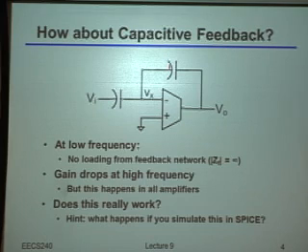Okay? Now, of course, if I have a capacitor, that is going to cause loading onto the output at higher frequencies, because just like any other capacitor, the impedance is going to drop. But that's going to happen in all amplifiers anyways. And in particular, as long as I can make this capacitance reasonably small in comparison to the load that I'm driving, it's not going to have a very big impact on my overall capacitive loading. In fact, if you remember, we said that we were going to have the series stack of these two capacitors, which means that I really get an even smaller cap than I would have thought just from any one of these two individually.